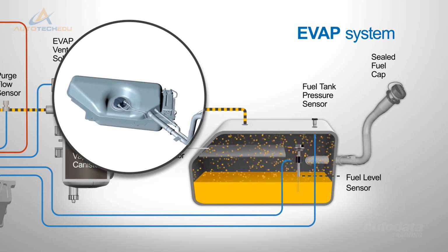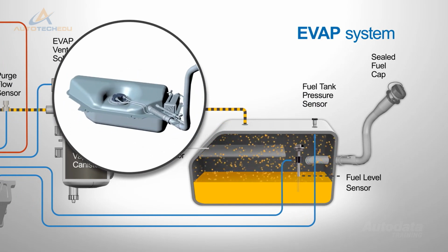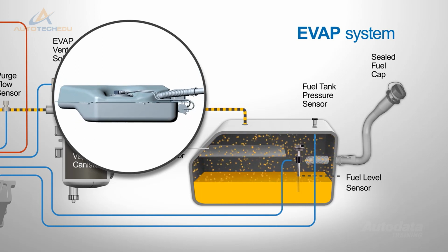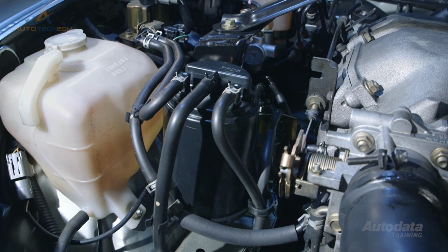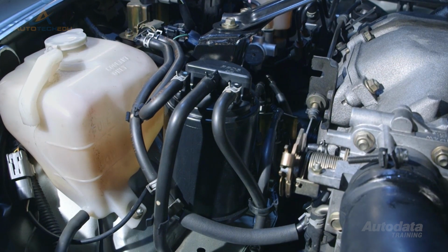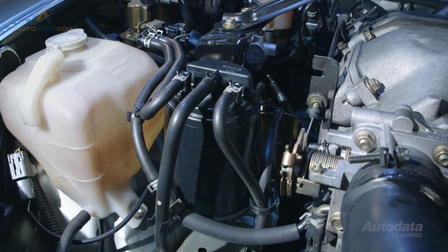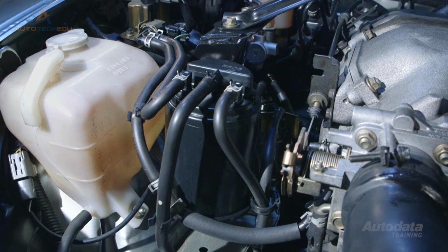The vehicle's fuel tank is a sealed unit and has been designed to prevent vapours escaping to the atmosphere. The fuel tank may have a separate chamber at the top to allow for expansion and contraction of the fuel vapour due to temperature changes. These vapours are collected and stored in a canister filled with activated charcoal, where they are held until purged to the vehicle intake manifold.